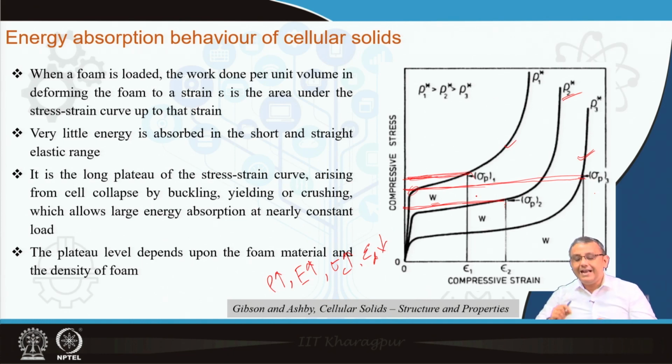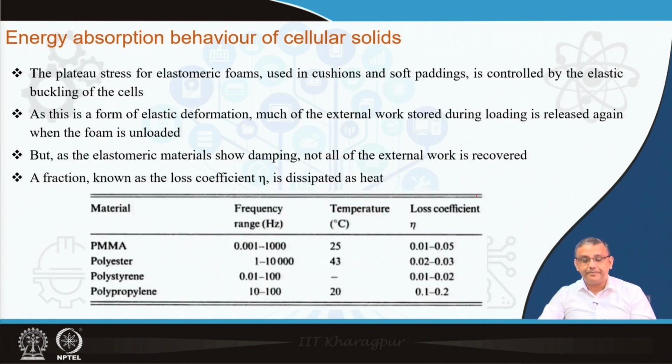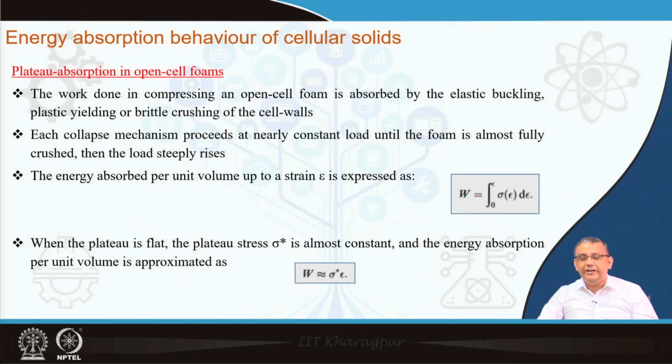So, you can see that, depending upon the foam relative density, the amount of energy absorbed varies, and we can actually control how much energy will be absorbed by controlling the foam relative density. Based upon that concept, these energy absorption diagrams were proposed, and we will briefly go through these in today's lecture.